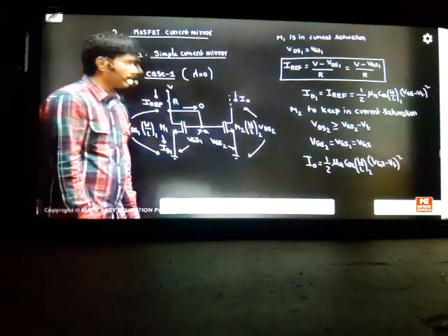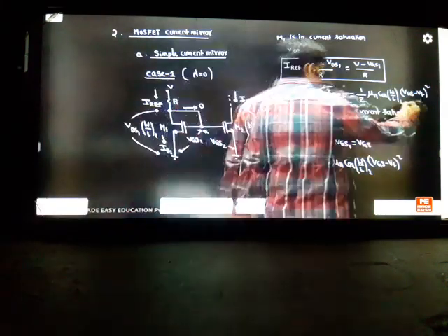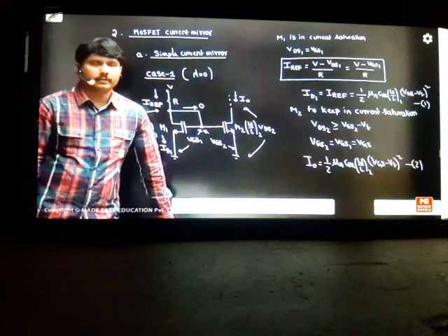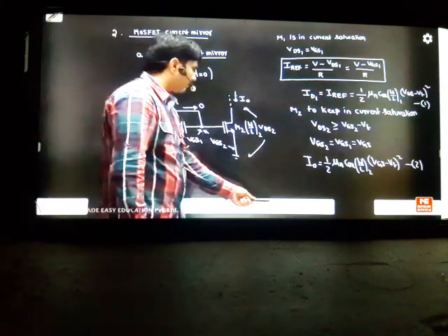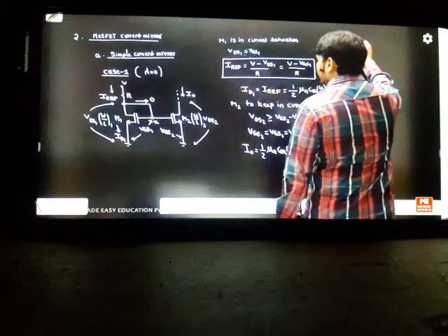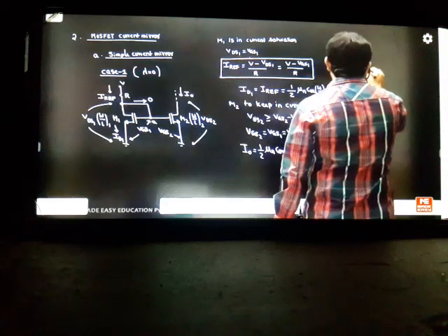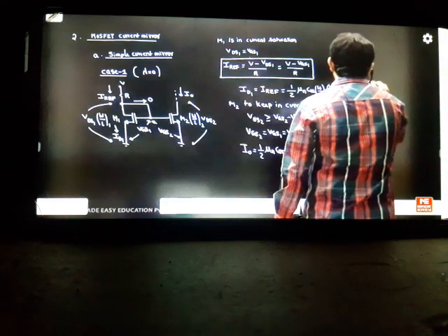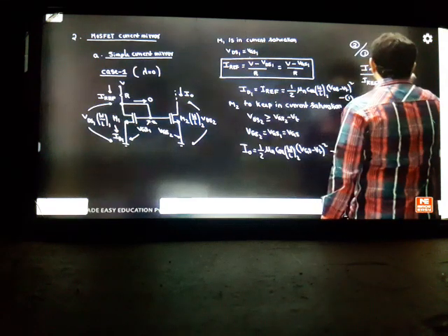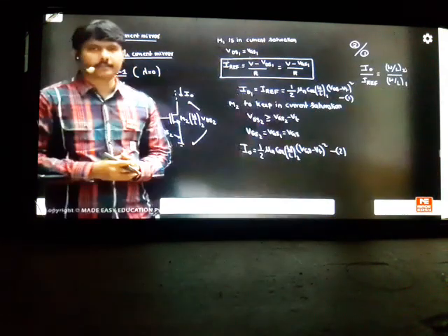So in both cases you are seeing two equations like this. The second transistor current saturation equation is like this, and the first transistor current saturation equation is like this. So from 1 and 2, this is 1 and this is 2, you have two equations. If I want to write the current transfer ratio technique, if I take the ratio 2 by 1, what answer will come? I0 by I reference will be equal to W by L2 divided by W by L1. You can see if I divide these two terms, you get the answer like this.